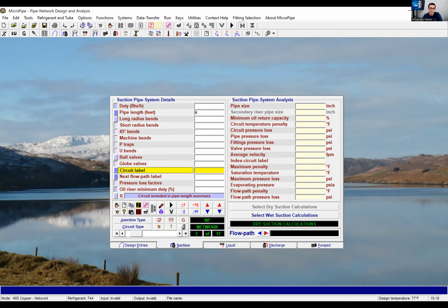And that's what's cool about CO2 refrigeration. You're going to be feeding from that flash tank receiver, that main liquid line, to your medium temp cases or loads, and also to your low temp loads. And that is what's interesting about CO2 for me, because there's so many different uniquenesses about it.